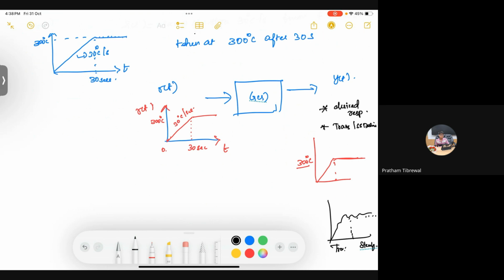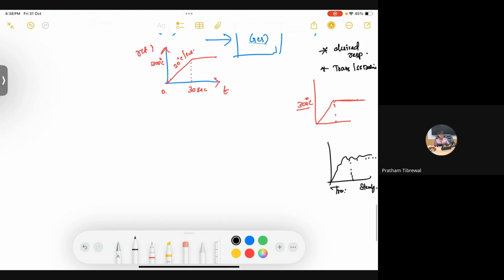But in terms of transient response or steady state response, we have different criteria. For example, when we consider only the steady state response, we always want the steady state error to be zero or nearly zero. This represents the system is behaving well, and if there is no steady state error, the system ultimately works in your desired performance range. So that is the understanding.